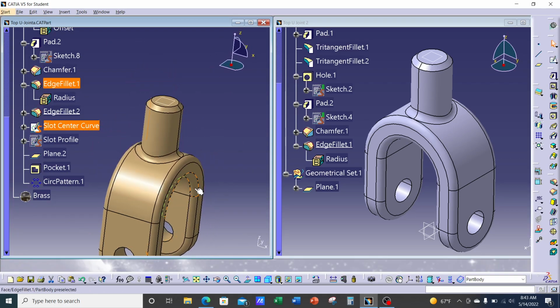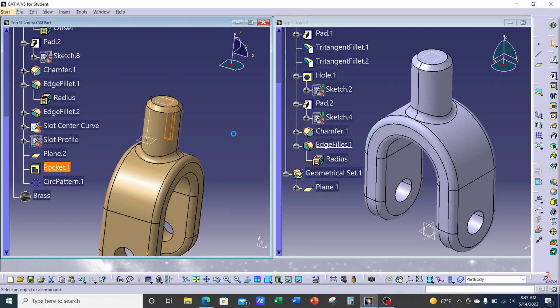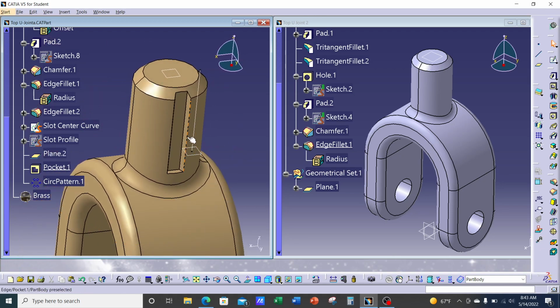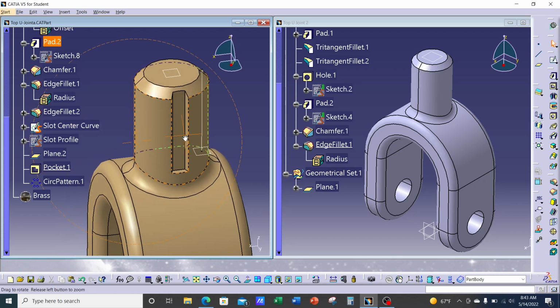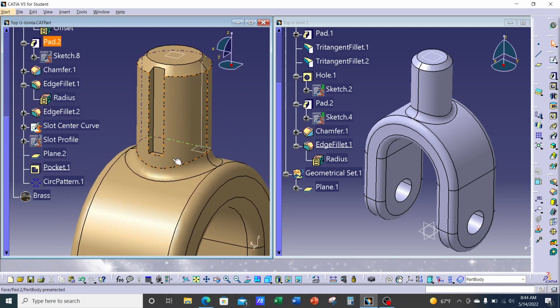The purpose of the line is to create this groove, right? So we're going to create a groove. So we need a direction, a line. And we're going to need a starting point. There's our sketch. So we're going to have to create a sketch of the groove and a sketch for direction.